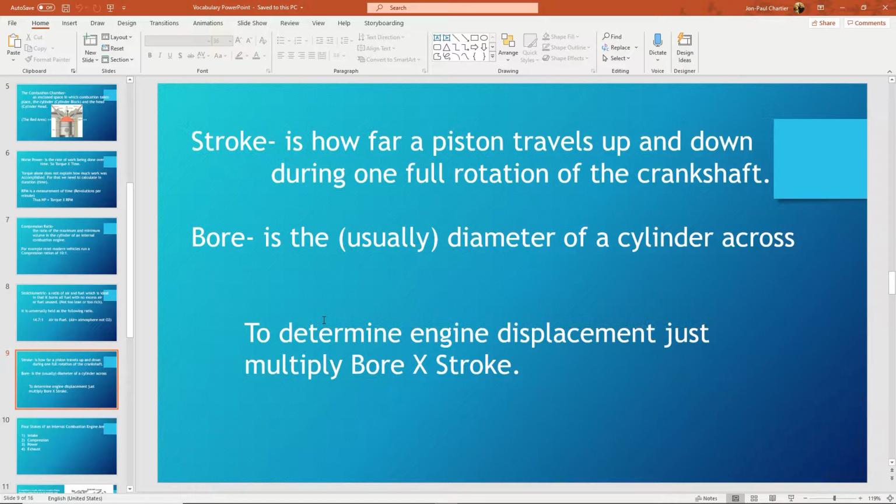The problem with the long stroke is you don't get very high RPM, and I can explain this simply. If I gave you a rope and tied it to a bucket and I told you to throw it this way and then turn around and snatch it and throw it the opposite direction, it would put a lot of stress on your arm and that rope every time it changed direction. If it has a long stroke, it builds a lot of inertia, and it's very difficult to stop it and turn it around and throw it the other way.